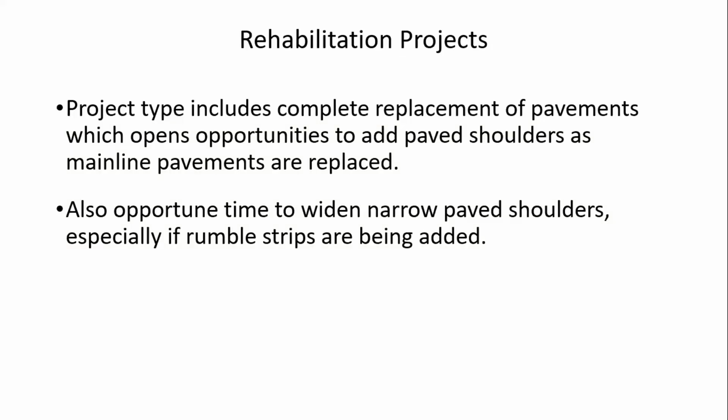On rehabilitation projects, the project type here includes complete replacement of the pavement, so that gives us opportunities to add paved shoulders as mainline pavements are replaced. Also, maybe a good time to widen narrow paved shoulders, especially if rumble strips are being added.